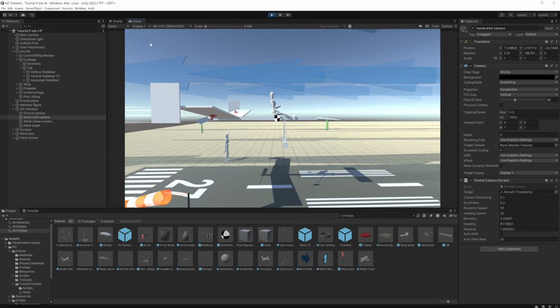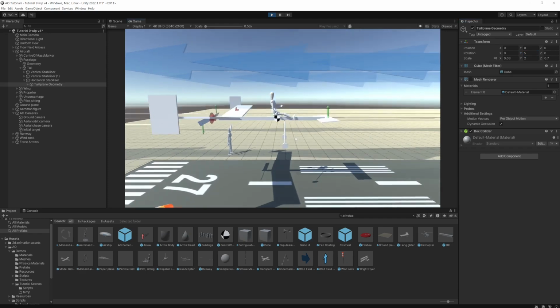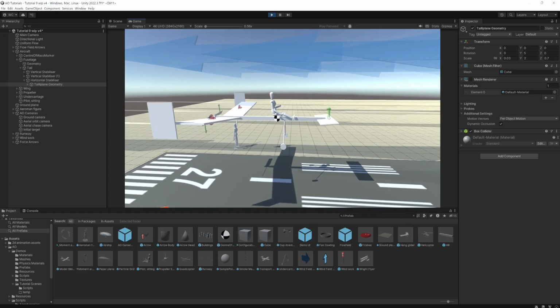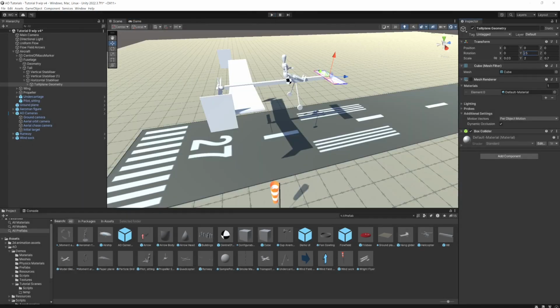So let's fix that. If we go to tail, horizontal stabilizer, tailplane geometry, it was at -5 before, so we can just flip the sign. Simple as that. We're doing this in play mode, and all the aerodynamics is handled for you. Our surface has gone the other way, and we can now see we've got a happy positive lift on the front there. In this circumstance, if it really was flying along with the wing at 0 angle of attack, the nose would get lifted up by the foreplane, and then this thing would start generating lift. Let's quickly make that permanent by coming out of play mode and changing that to 5. Go back into play mode.